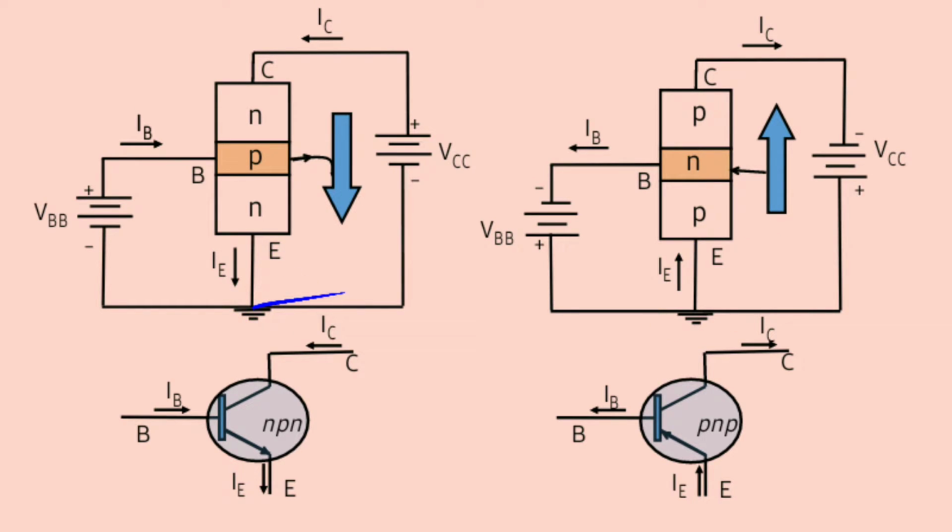The emitter, base and collector currents are shown in their actual conventional current direction. Even though the transistor configuration has changed, the current relations developed earlier for the common base configuration are still applicable. And proper DC biasing should be applied for both types of transistor in order to get the proper regions of operation for amplification applications.